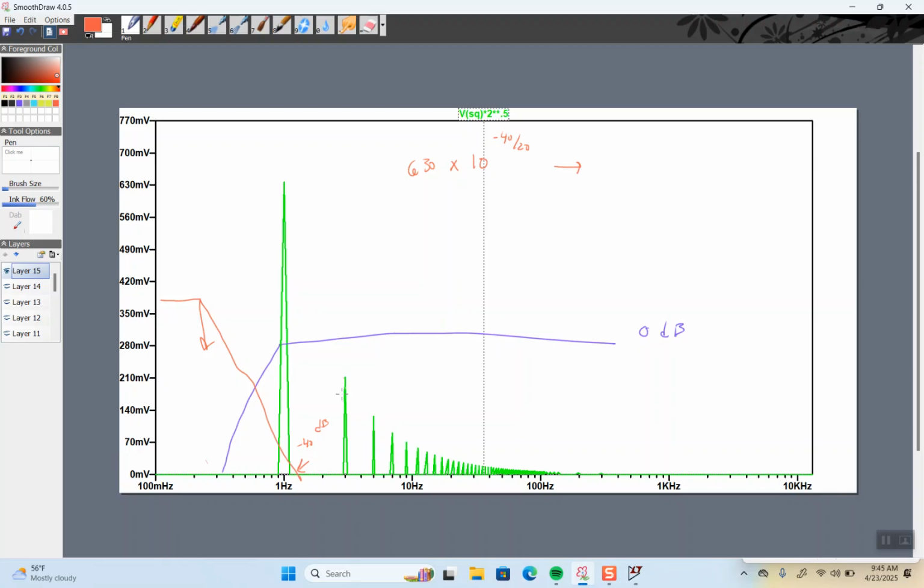And a first order filter would go down by 20 dB per decade. So there is some of this signal coming through, right? But the higher the frequency, the more of it's attenuated. This frequency is, when we're doing the pulse width modulated DAC, the one you're really trying to get rid of. And so you might want something sharper. Again, it never goes to zero.